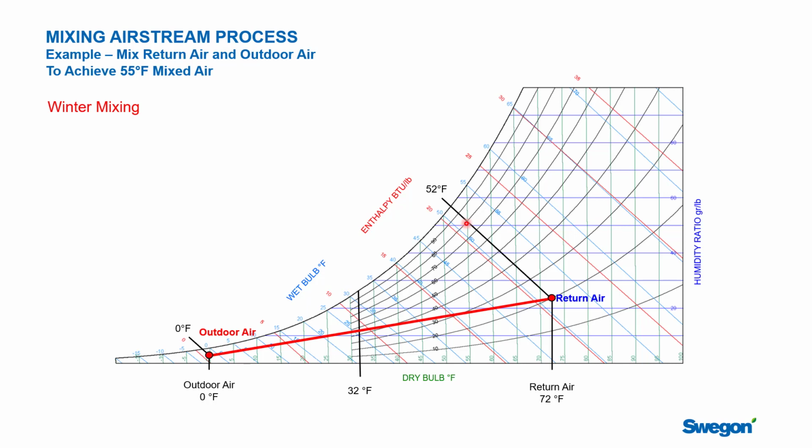So it could be a VAV air handling unit on a typical project, and you have this opportunity of mixing warm return air from the building with outside air. And so this time we're going to ask the question the other way around, which is, if you know you need to be at 55 degrees, what's the mixing ratio that you need to deliver 55 degrees?